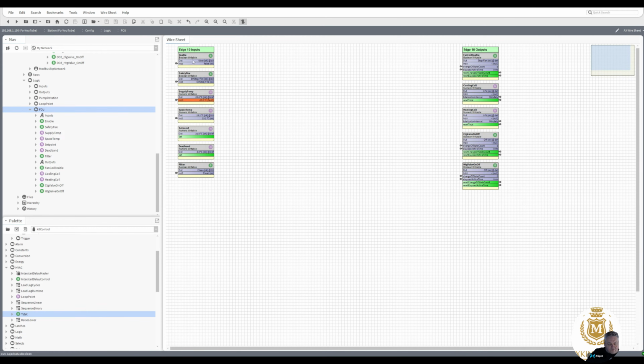So first of all, I've just put some points onto a wire sheet. It's for the example set point. I've just put what we think the set point is, but that's going to be made adjustable, and the dead band from the set point. So if it's 21 degrees, 22 degrees and 20 degrees is your dead band, or we can do 2 degrees either side. I don't know yet. Let's have a play with it and let's see where we go. So we've got the points on there.